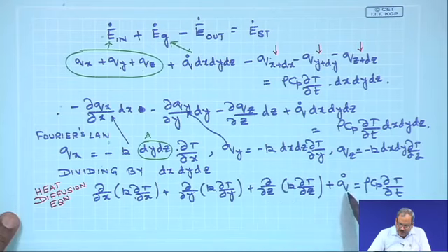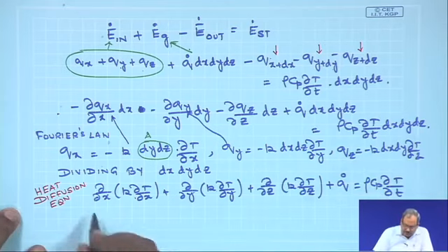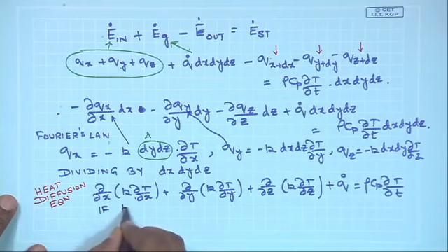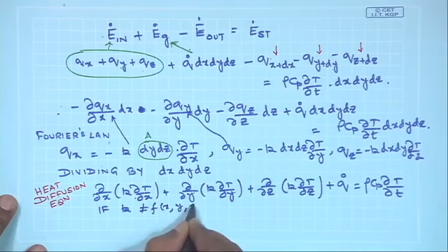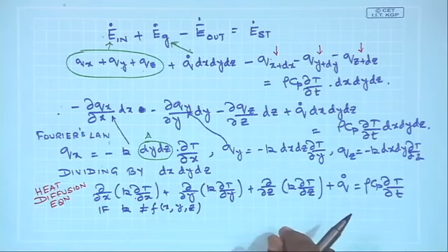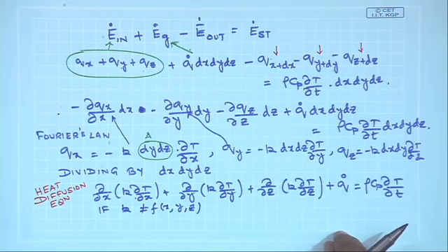This q dot is the energy generated per unit volume, T is simply temperature, rho is the density and Cp is the heat capacity of the system that we are dealing with. If k is a constant, that means it is not a function of x, y and z, that means the system is isotropic, and by isotropic I mean that the system properties do not change with direction.